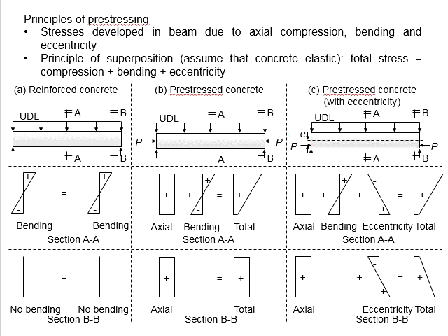In short, for you to analyze the stress within a prestressing member, you need to consider all the effects of the external load acting on the member. After you have established all the stress diagrams, then apply the principle of superpositions.